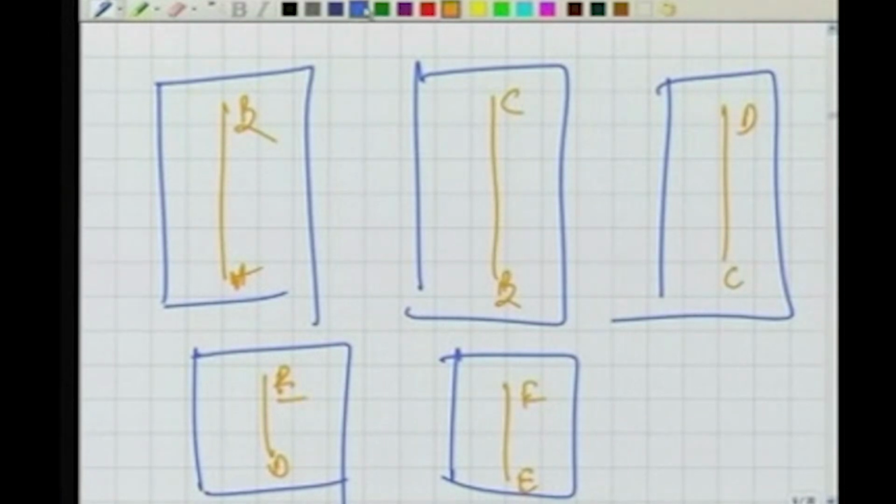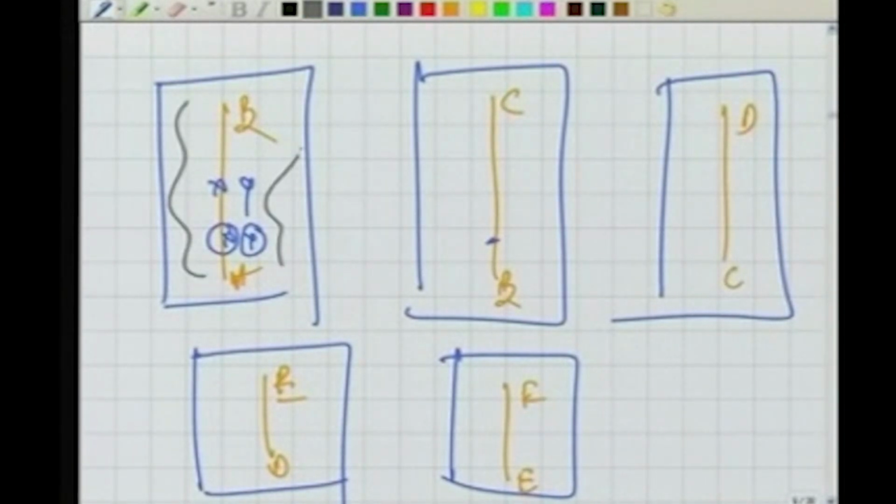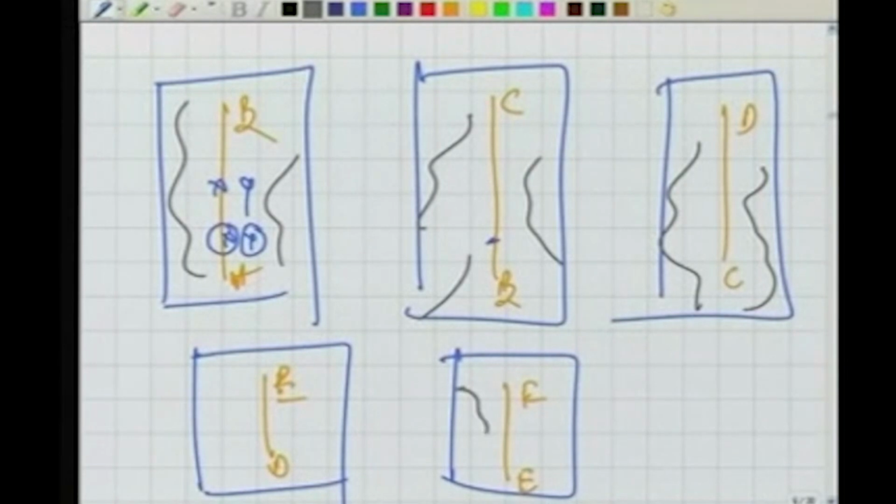And we also have the values of the chain edges, X, Y, the chain edge and the offsets, all written everywhere. And also we have the approximate or rough idea of the area, the rough sketch of the drawing, here in the field book.